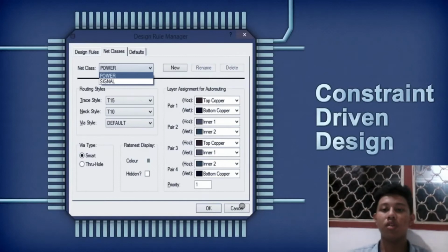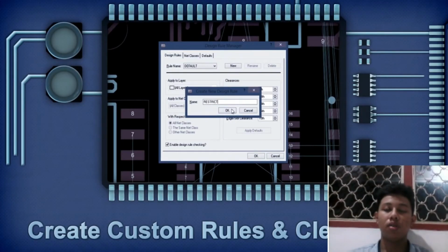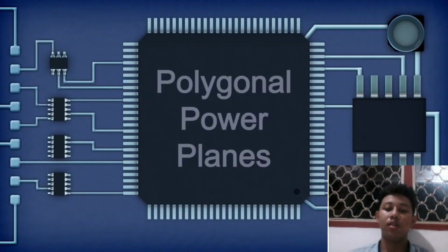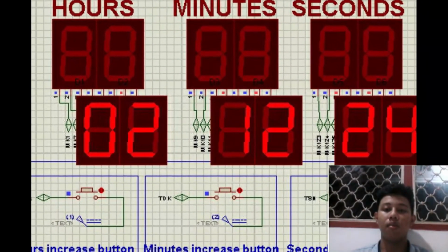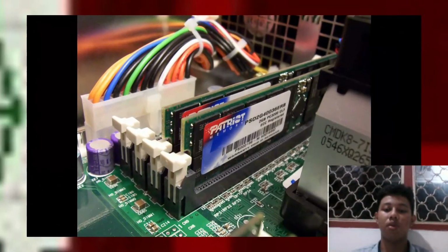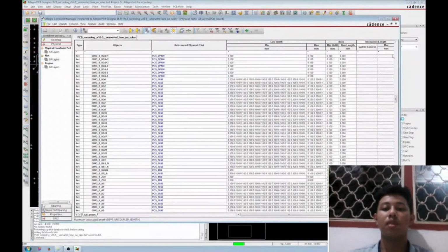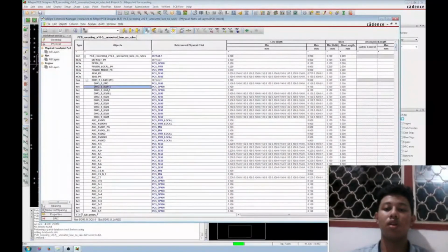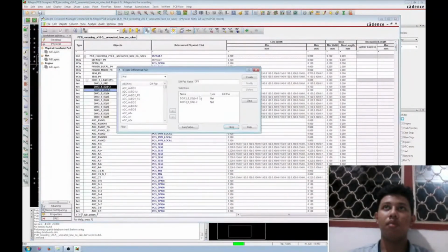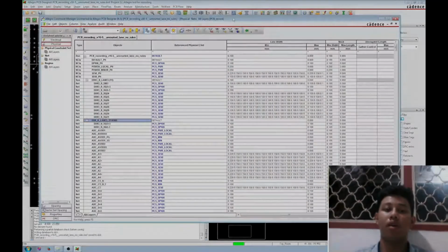And I will explain about ATmega32. ATmega32 is a microcontroller produced by Atmel. This microcontroller has a high clock and works up to 16 MHz. The size of the flash memory is quite large. Its RAM capacity is 2 KB. In the ATmega32 CPU architecture, the main function is to ensure the instructions are executed correctly. The program memory is used to store the program and the SRAM to store variables.